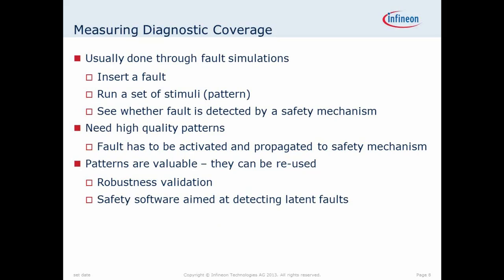So you need to demonstrate diagnostic coverage. Typically, how do you do this? The standard way is through fault simulations. You insert a fault, you run a set of stimuli, and you see whether the fault is detected by a safety mechanism.